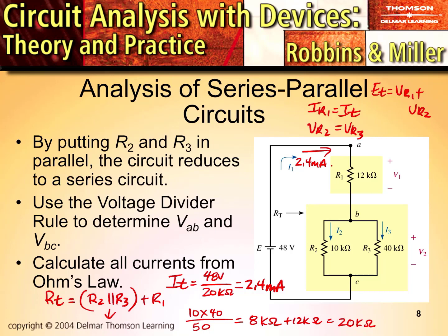We've calculated our total current. Now we can determine our voltage division based on IR values. And the simplest way to go about that is to determine the VR1 value that we see here is the one that's conducting total current, and then you can subtract that from the applied voltage. That's using Kirchhoff's voltage law.